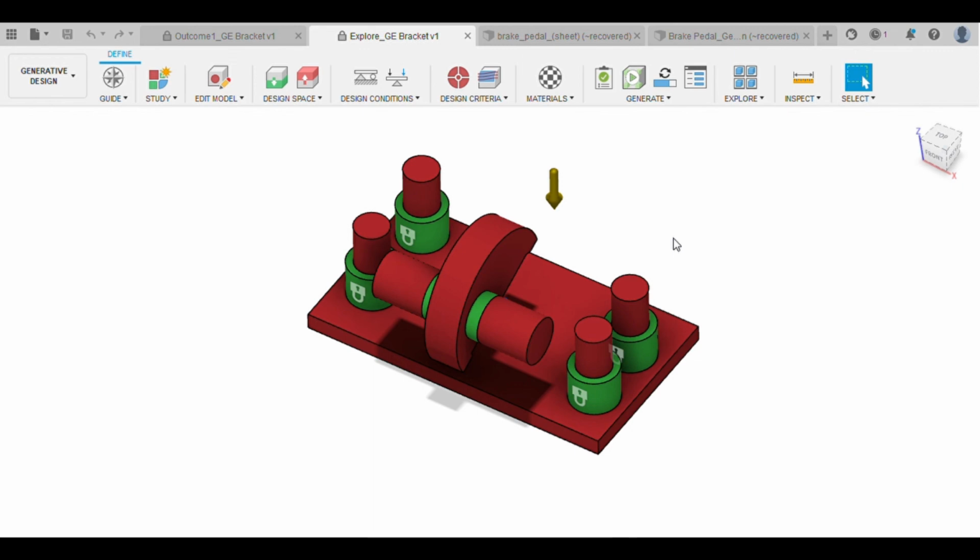So in the optimized manner of material flow, in the red color indicated obstacle geometry regions material should not flow. On the regions where assembling of components takes place, if the material flows into that geometry, the assembling process would be much more difficult. So to align these considerations we use this obstacle geometry.